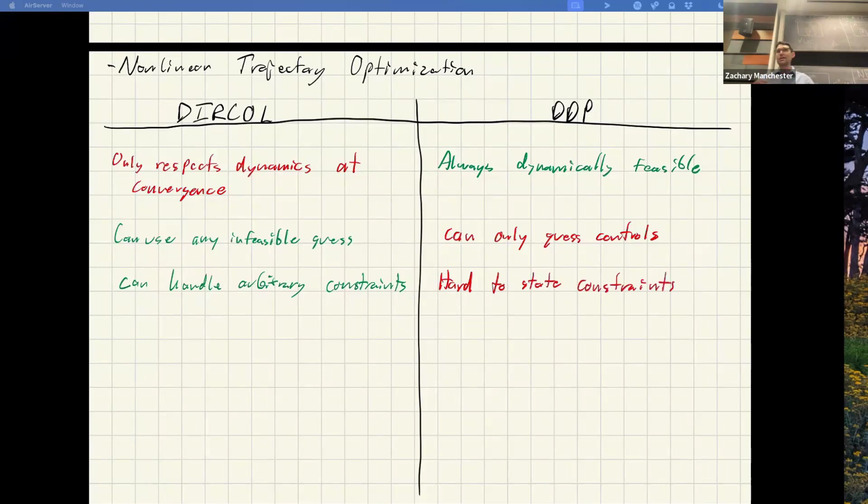And there's ways to do it, but it's all kind of hacky and a little messy and not great. Okay, so then talking about tracking controllers, like we were just talking about, right? Tracking something you've optimized. With DDP, you essentially get that TVLQR tracking controller for free. At convergence of DDP, the K matrices are the LQR tracking controller that you would get anyway. So that's kind of cool and possibly useful.